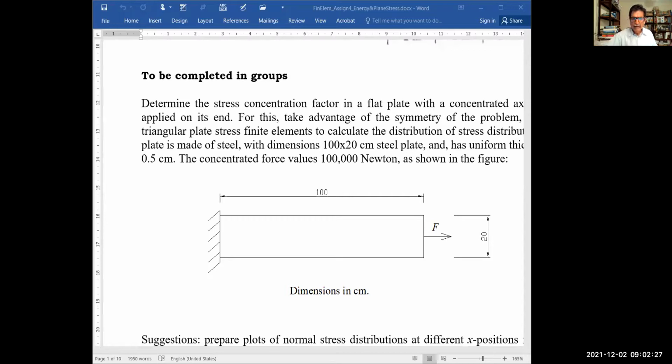If I have a plate like this one here, and I apply a force at a point. People, this is not a distributed force on all the edges. Let's suppose you apply a force in the center of the section. What happens if I make a cut? Probably you studied this in solid mechanics. If you make a cut here and analyze the distribution of the stress, you're not going to have something like this. You are going to have something like this.